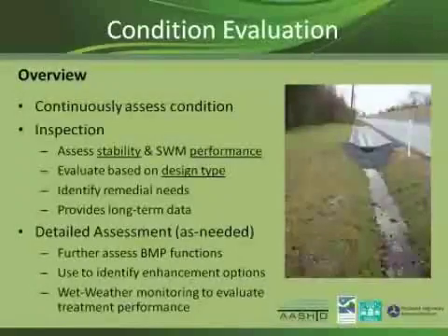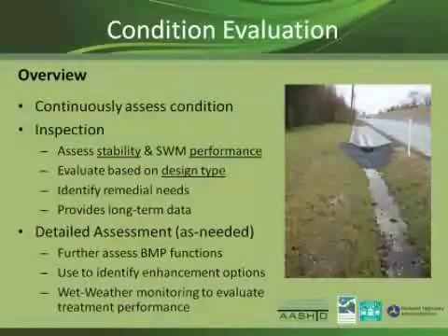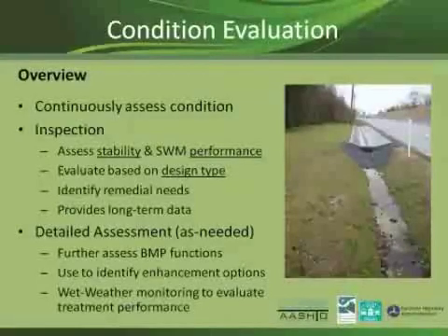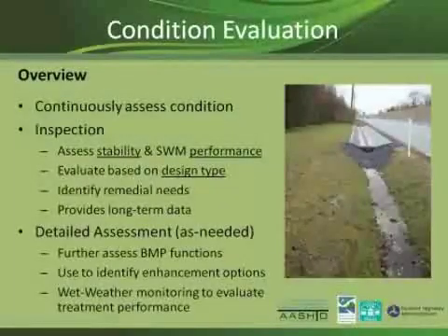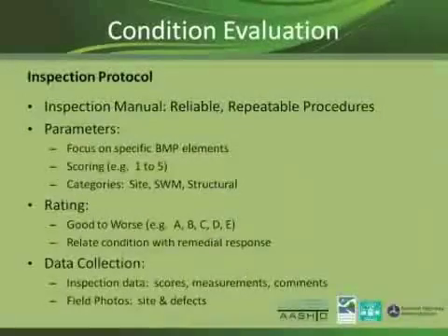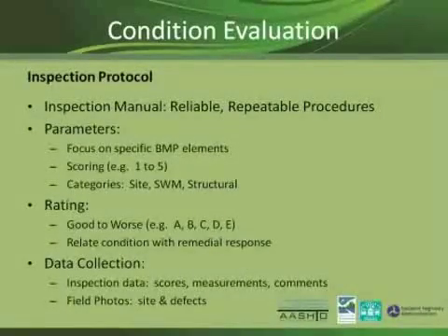Inspections are also geared towards recognizing your remedial needs, but the value of it is that as you collect data over time, it's going to give you some long-term data to work with. And as needed, you may need to do some detailed assessments. You may need to drill down to a specific site that's problematic, or you may be looking at different BMP types, for example, infiltration devices. Sometimes we put them in the ground thinking it's a great spot, and sometimes they don't work out. Detailed assessment can also include using wet weather monitoring to help evaluate your performance.